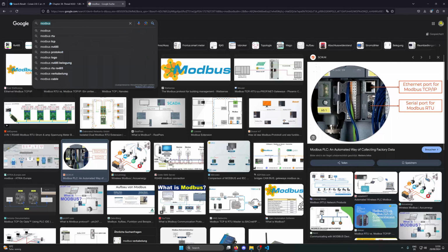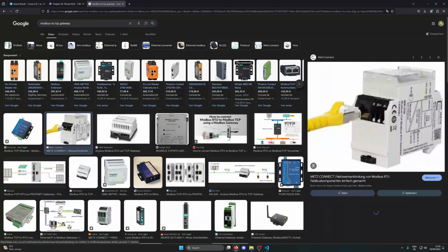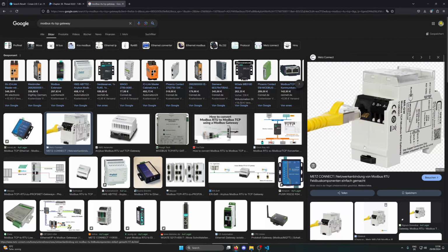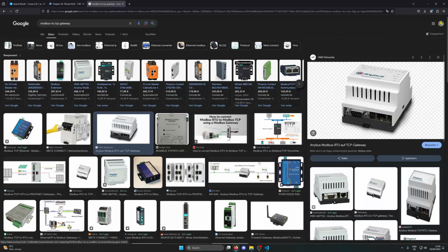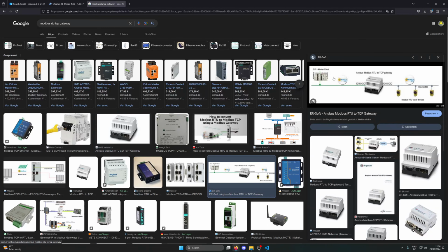I think you can have a Modbus RTU TCP gateway in between, which allows you to connect the network on the one side and the classical bus on the secondary side. And the way Modbus is built, it should work without any big configuration to just talk via the TCP protocol to the RTU devices, which is really, really cool. If you know how Modbus works and you integrate it into your software, it's really, really nice.